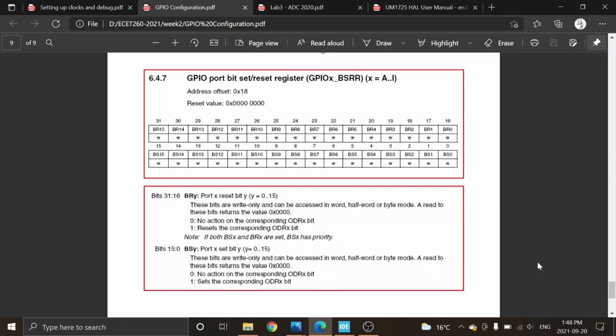Yeah? Sorry, is the address offset just assumed as soon as you type in GPIO? Yeah. If you actually, and we'll highlight some of the functions, you'll see it actually goes and does it. So when you go HAL GPIO write, it's calling this stuff. Okay, and so you could go and write those individually, but it's doing that, and we can actually go in and see it.